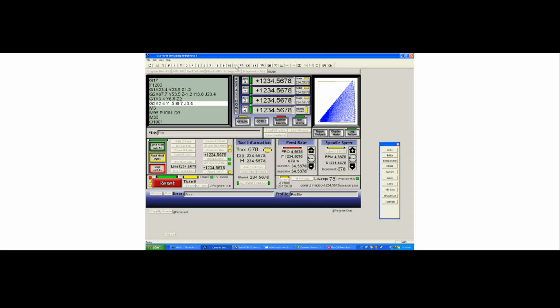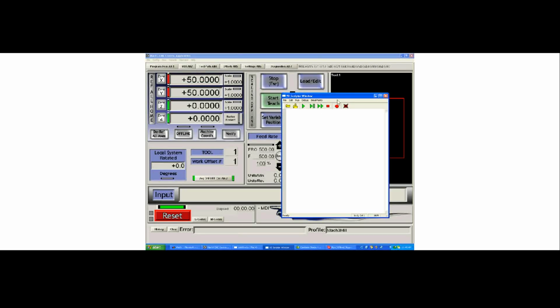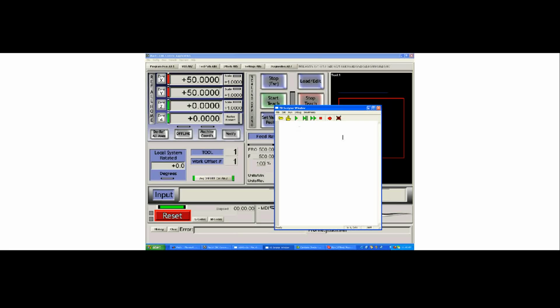And you'll get pretty handy at that if you practice with the Visual Basic Scripter and begin to understand what the commands do. Again, I encourage you to open up the scripter, load a few macros, hit play and see what happens. Make sure that your control is reset and ready to move when you're hitting play on a script if you wish to see the end effect of it. You don't have to save it as a file. You can simply open up the Visual Basic Scripter, type a command like Code "G0 X10", and by hitting play, your X will move to 10. Play with the commands, play with other people's scripts, get used to the Visual Basic Scripter.